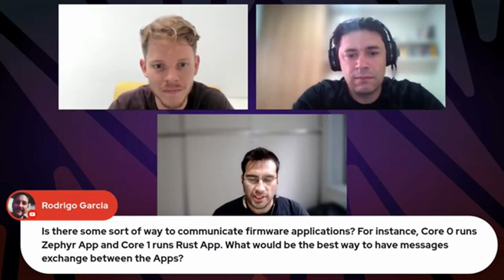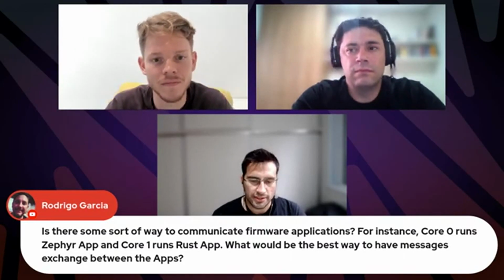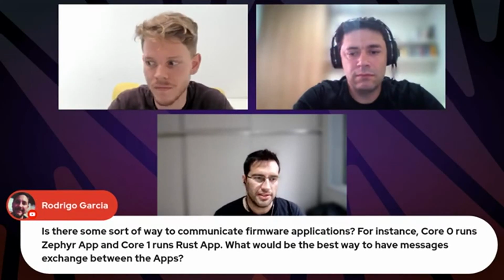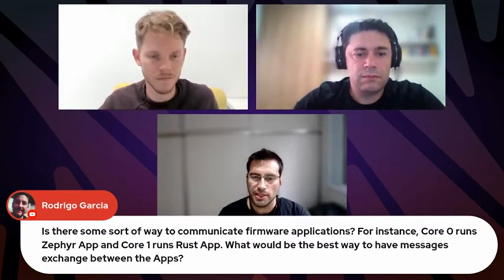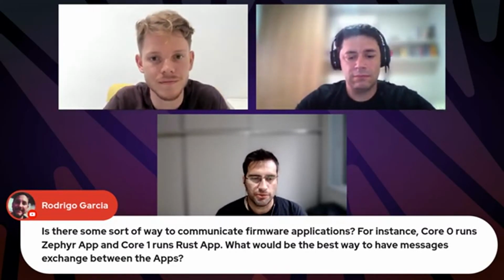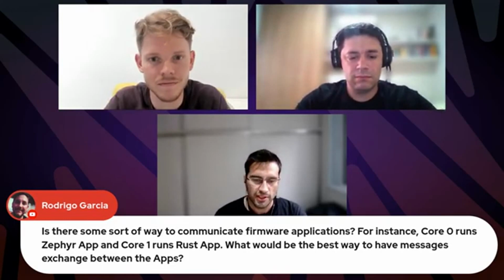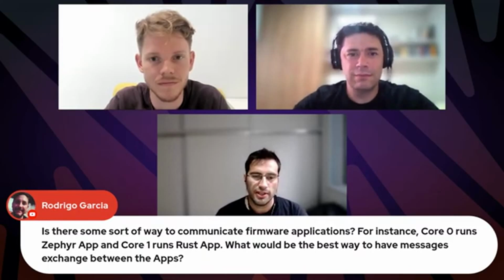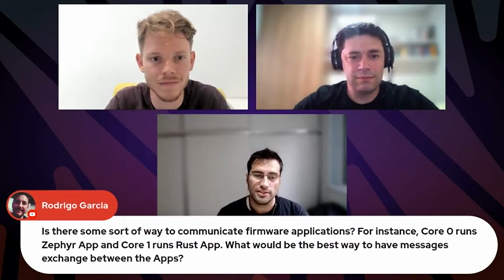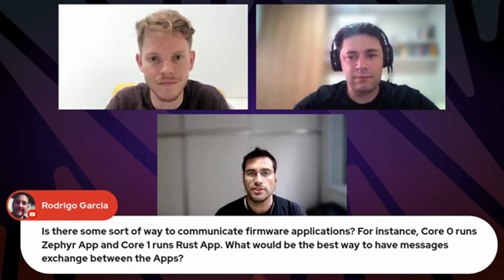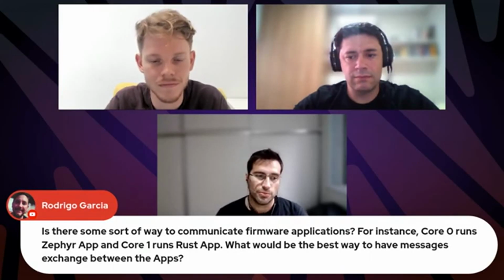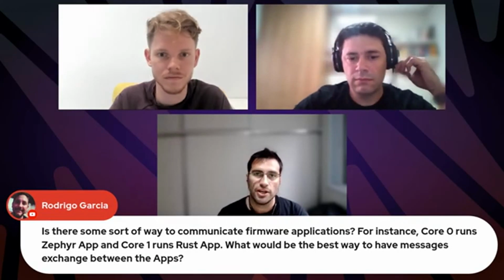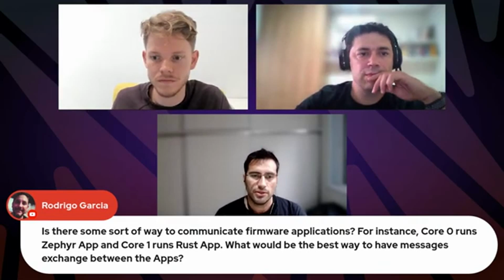Yeah, so when it comes to Zephyr, we implemented a soft IPM. IPM is the interprocess messaging. So in Zephyr, we have the IPM, which is the interface responsible for exchanging messages between both cores. This IPM interface has 4 channels. Channel 1 is for the Wi-Fi packets, channel 2 is for the Bluetooth packets, and channels 3 and 4 are for application custom packets. Each channel supports 64 bytes. So it's up to the application to handle larger packets.